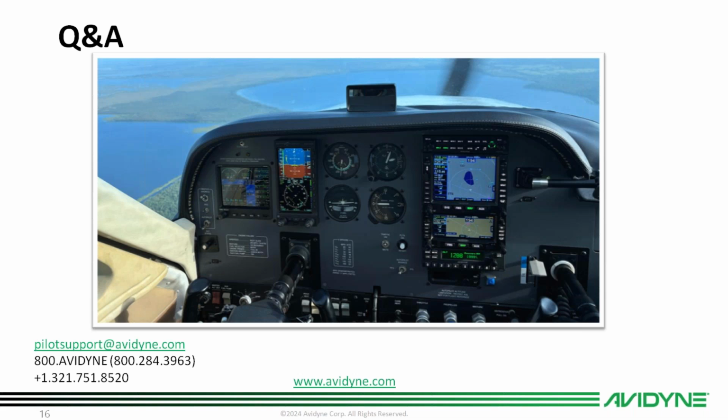The only thing I caution is if you're cleared to descend via the arrival route, a direct to a waypoint forgoes all the previous altitude restrictions. If you do a direct to, it's going to cut you directly to that waypoint instead of along the route. I would have to test this out myself, but I would side on no, that you cannot delete the waypoints in an arrival.